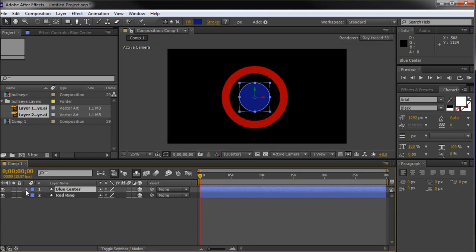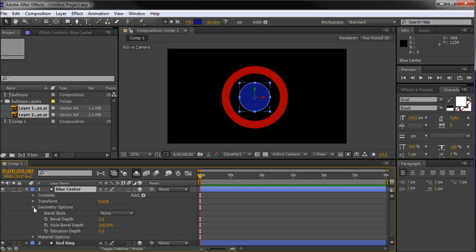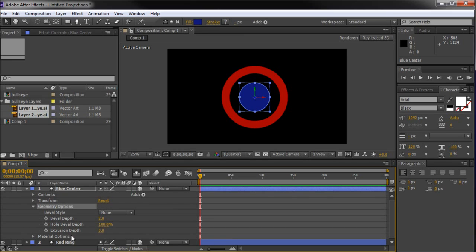Anyway, so moving on, what we're going to do is go to our geometry options. If you followed along with the text tutorial or one of my previous tutorials on this feature, then you're probably going to be able to go on from here without actually watching this. But if you haven't seen that video, then you're probably going to want to follow along still. So I'm going to open up geometry options, and what we're looking for is extrusion depth. So I'm just going to turn that up to, say, about 75.